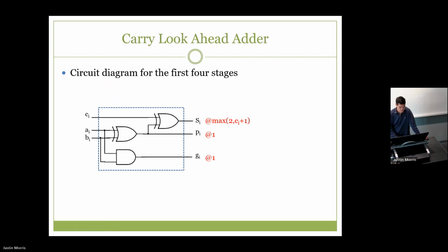Okay. So here are our individual little bits now. We have this propagation. And then we have the generation. And the reason that it's this XOR is because it mentions in the previous slide that rather than the OR, you can do this actually. And then because of this XOR already existing for the full adder, we're kind of using it as double duty, right? We can reuse this hardware for a different purpose.